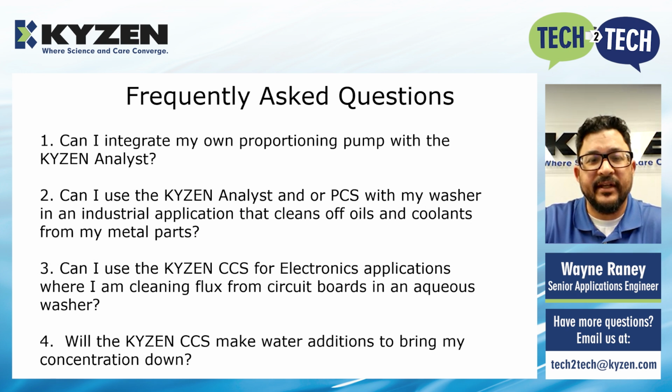And so some of the frequently asked questions is, can I integrate my own proportioning pump with the KYZEN Analyst? The short answer is yes. If your pump can receive a 0 to 10 volt DC or 4 to 20 milliamp signal, then it can make additions.